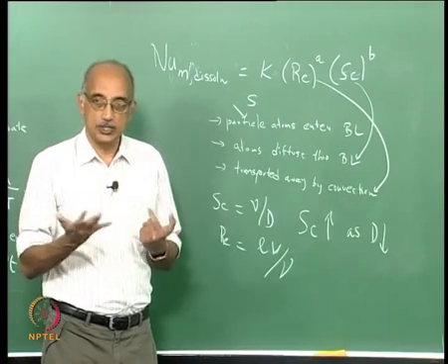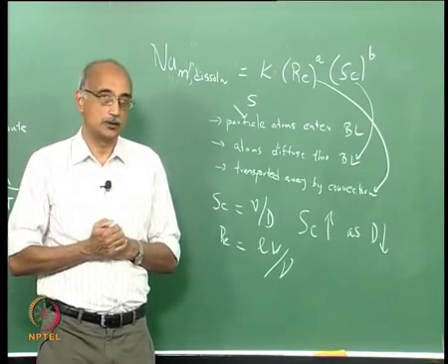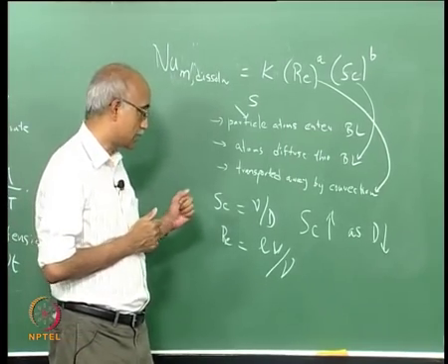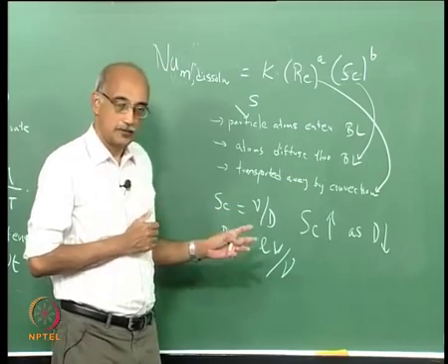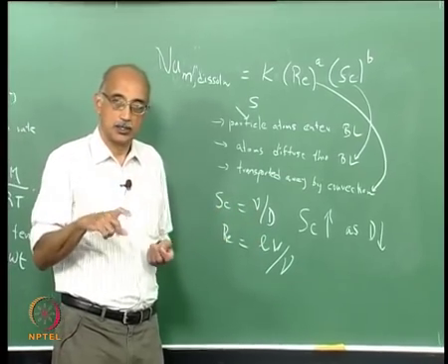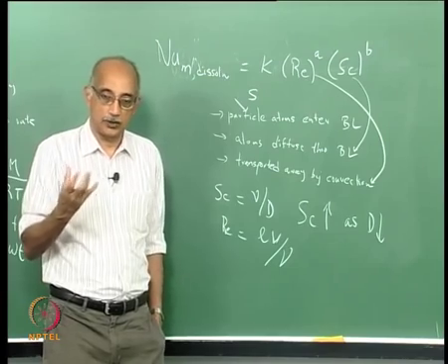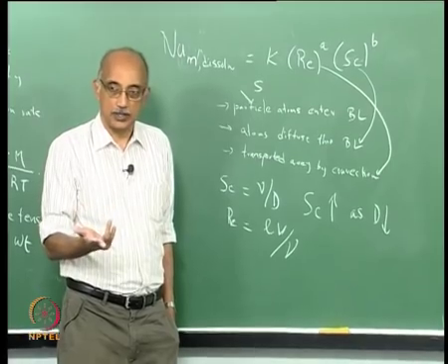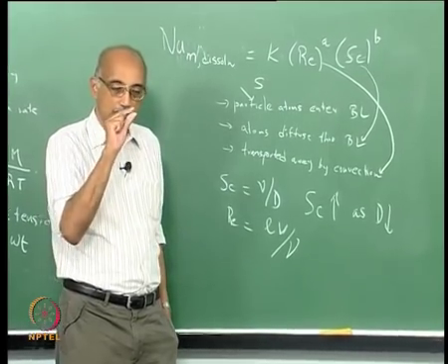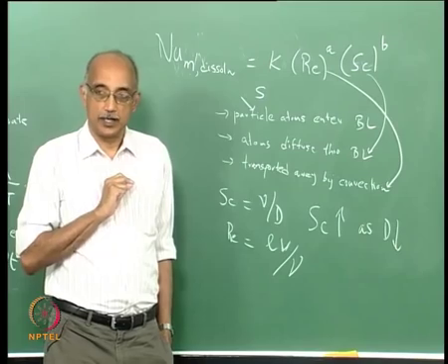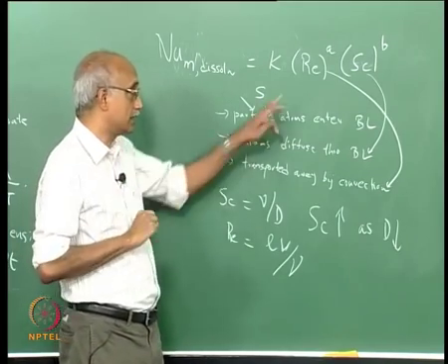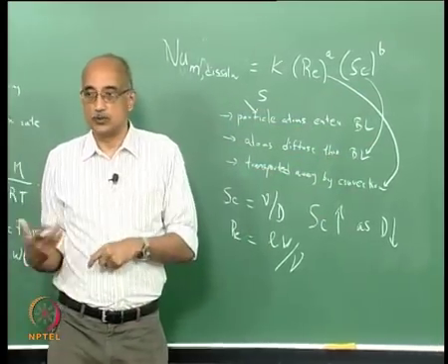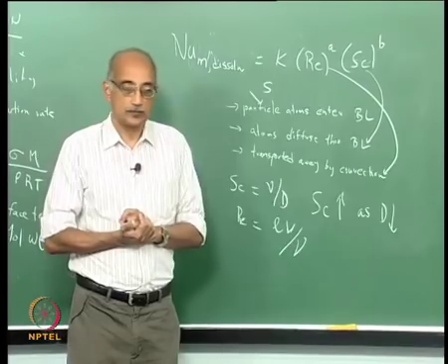So, high frequency acoustic vibration is frequently used to again improve dissolution processes, and the way that works is actually twofold. Unlike stirring, which really only affects the convective portion, if you actually add an acoustic process, a vibratory process, it will have two effects. It will induce a convective effect, but at the same time it will also reduce the thickness of the boundary layer. And therefore acoustic methods can enhance both the convective portion as well as the diffusive portion of the dissolution process.